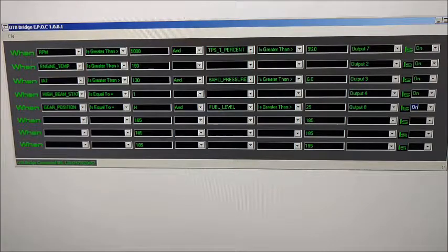The E.P.O.C system allows you to control the bridge outputs on and off based on any of the engine operating parameters. With this system you can take up to 2 engine operating parameters, set limits, and turn outputs on and off. This is really useful for controlling things like engine fans, nitrous oxide, water methanol injection for turbo applications, and even auxiliary warning lights. I'm sure that you car builders out there can come up with all kinds of good uses for this control system. Let's take a look at the software and see exactly how this control system works.